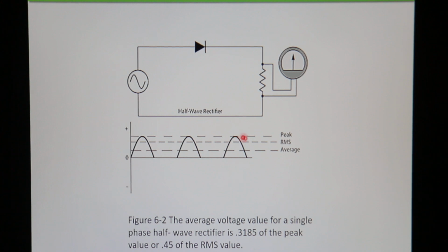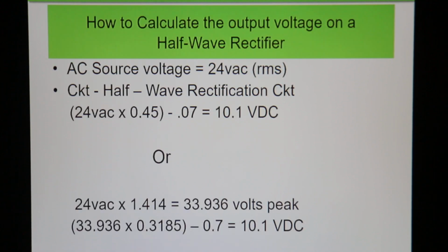Or I could actually know the RMS value of this sine wave and multiply that times 0.45. Okay, so two different ways I can go about calculating that voltage. So I'm going to show you, I think on the next slide, you will see how we will calculate it,